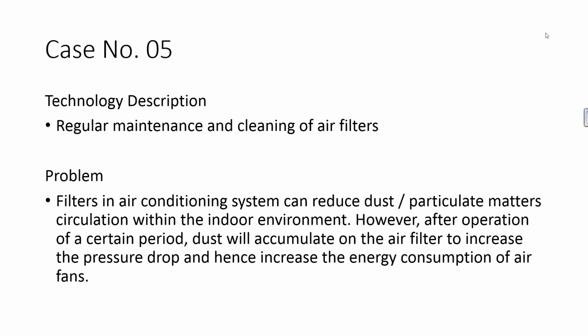Okay, the last case: regular maintenance and cleaning of air filters. The problem: filters in air conditioning systems can reduce dust and particulate matter circulating with the indoor environment. However, after operation for a certain period, dust will accumulate on the air filter to increase the pressure drop and hence increase the energy consumption of all fans.